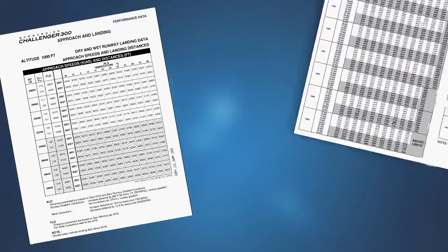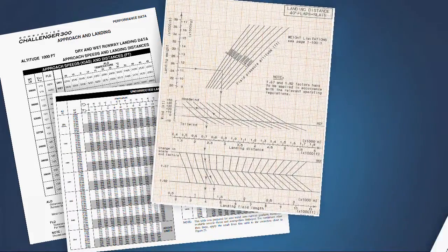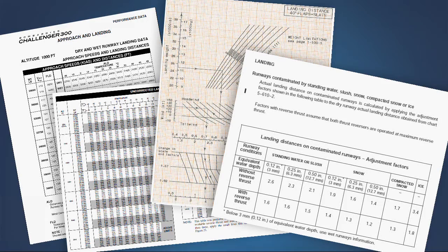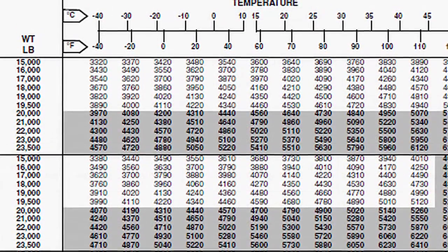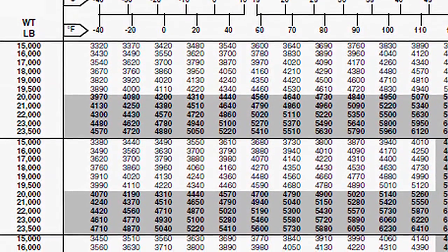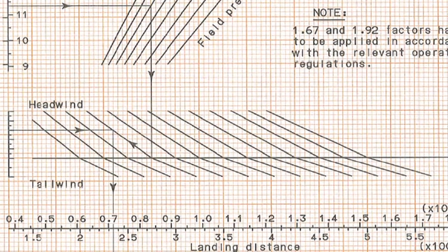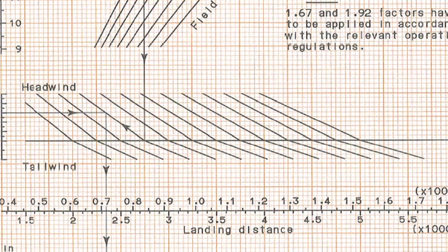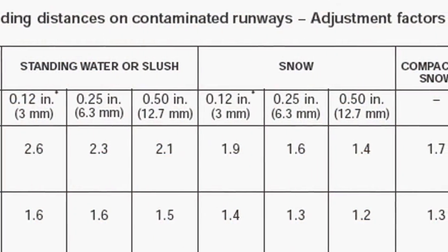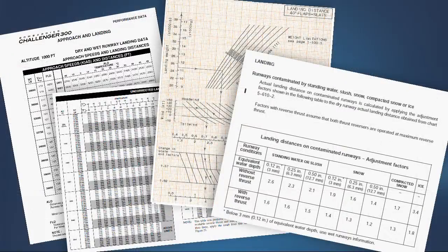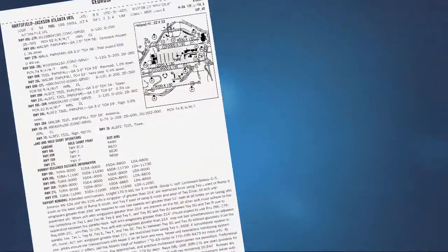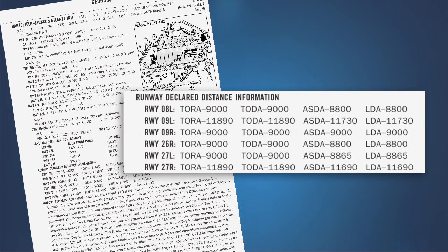The airplane operating rules and/or airplane operating limitations establish minimum distance requirements as well as weight limitations for takeoff and landing, and are based on performance data supplied in the airplane flight manual. The minimum distances required for takeoff and landing, obtained either in planning prior to takeoff or in performance assessments conducted at the time of landing, must fall within the applicable declared distances before the pilot can accept that runway for takeoff or landing. Declared distances are published in the FAA Airport Facility Directory for runways where they have been established.